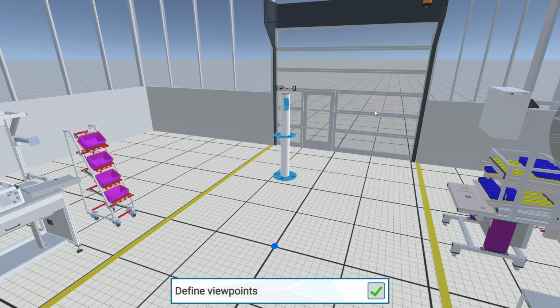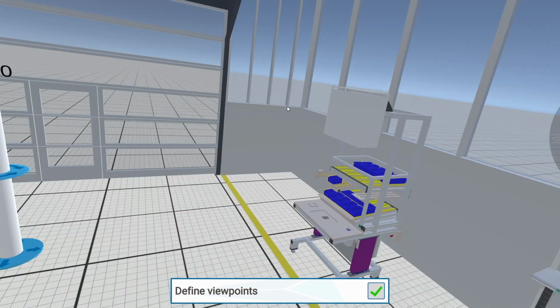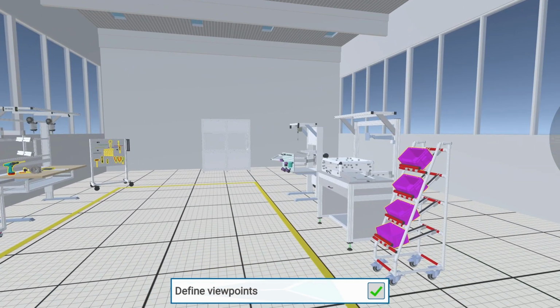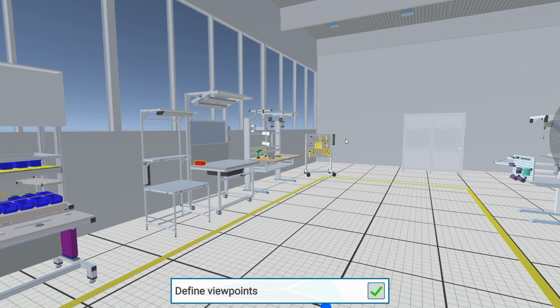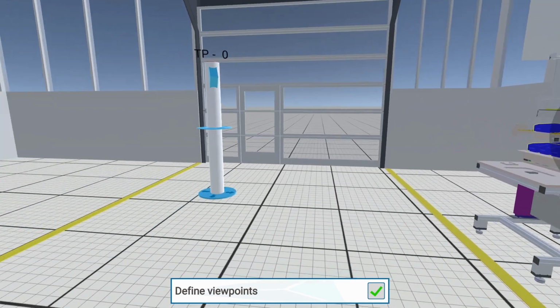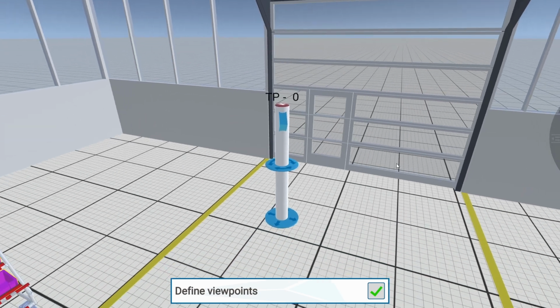As soon as a user is at a viewpoint, he can change his perspective freely, but remains at the fixed position in the room. By left-clicking on the arrow, you can try out the viewpoint and adopt the perspective of the viewpoint. You can continue to move freely and leave the perspective of the viewpoint using the usual W, A, S, and D movement buttons.